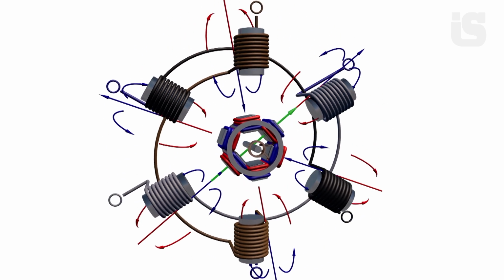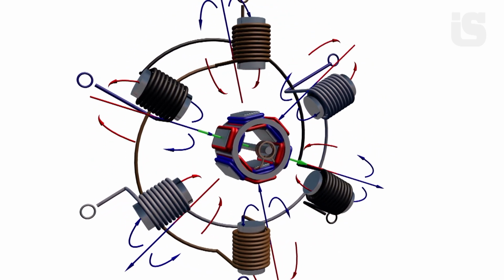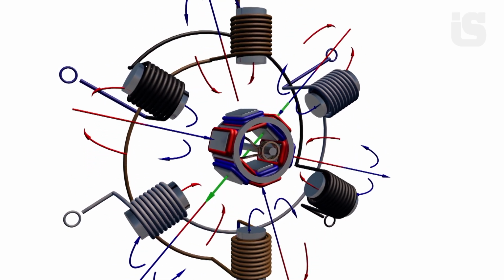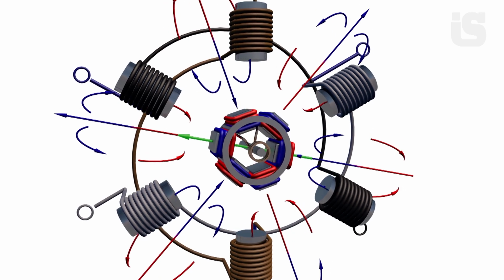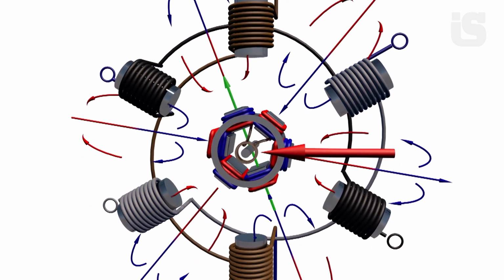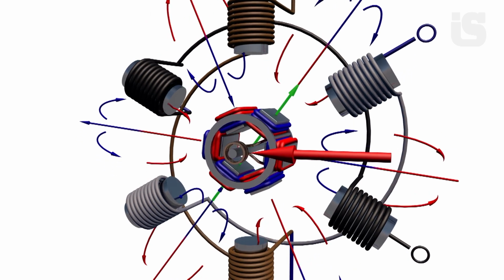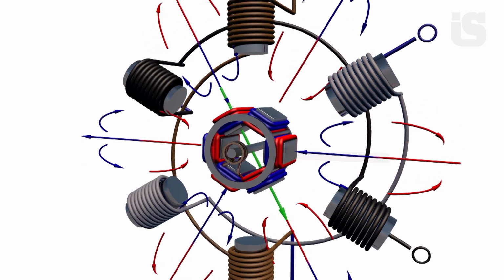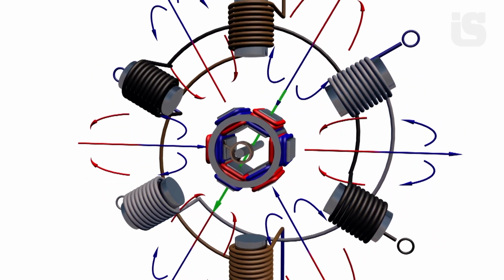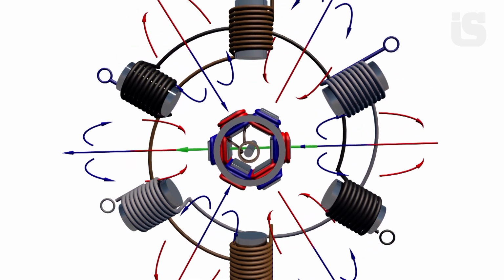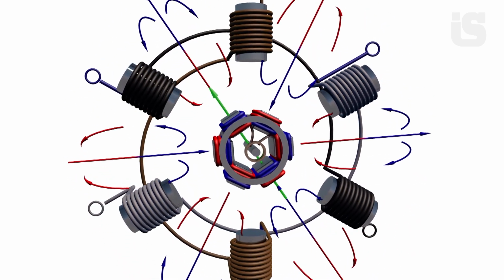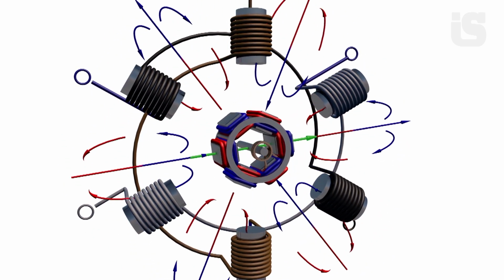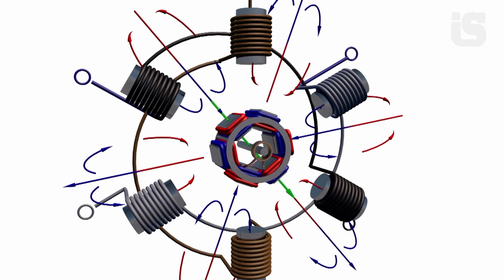Electromagnets can also be used in the rotors of a synchronous motor. The rotor of a synchronous motor has an excitation winding with an independent power supply. A direct current is supplied to the rotor winding through slip rings. Each individual winding acts as an electromagnet. The electric motor then operates similarly to a permanent magnet motor. These motors have a rather complex design due to the presence of a brush assembly. Additionally, they require an external DC power source to operate.